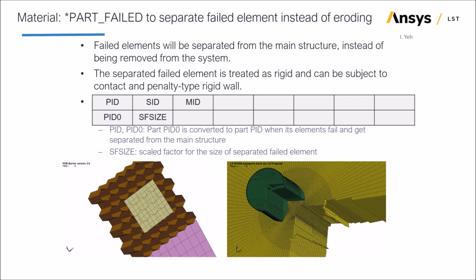When elements reach a failure criterion, they would normally get deleted, but that can give very unrealistic results for some types of problem. In reality, the broken bits of material still have mass and can still pile up and generate friction against each other. And if we model the elements disappearing, you miss an important contribution to the load.